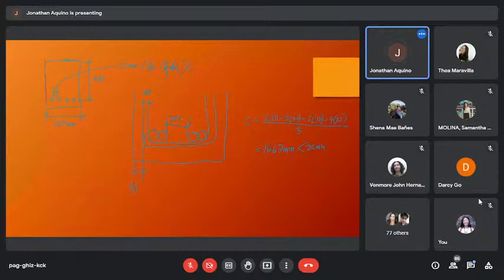Pag 2-bar bundle, the clear spacing C is 250 minus twice the concrete cover minus twice the diameter of stirrups minus 4 times diameter of bars divided by, since one spacing na siya, 1 lang siya.